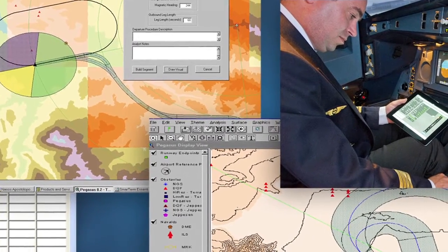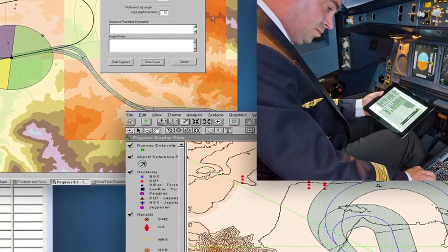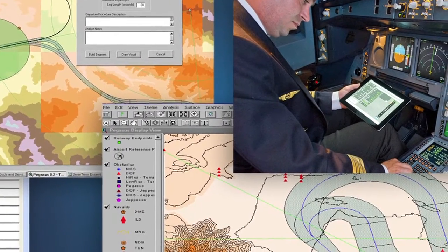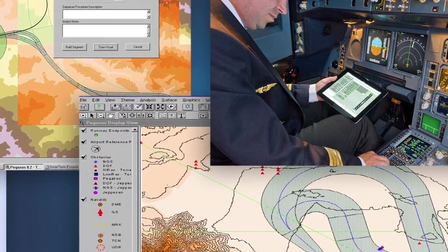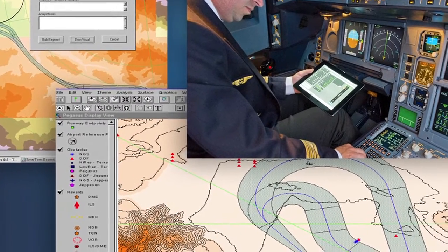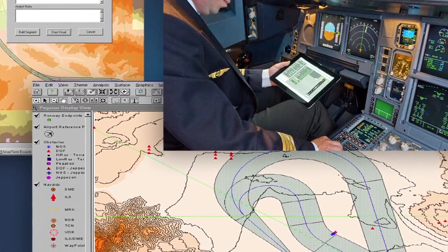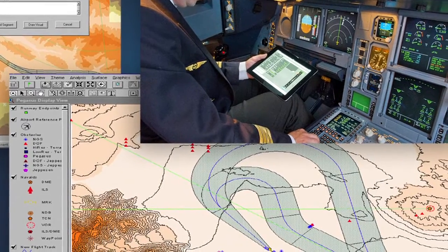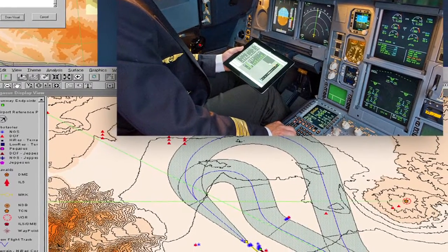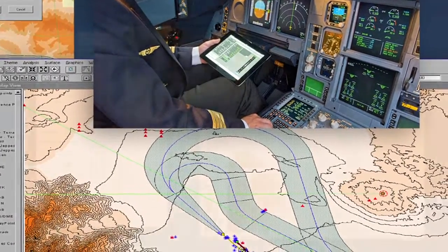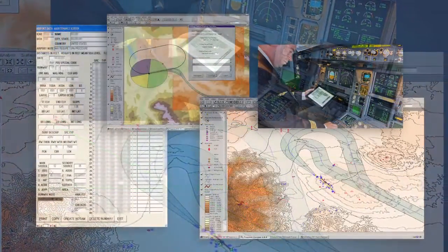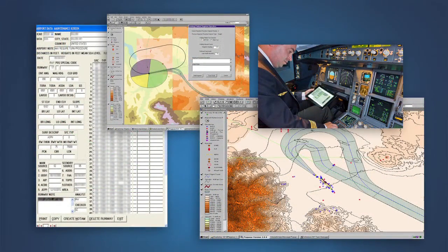Performance engineers will most often use the airplane flight manual data to create a more practical means for pilots to evaluate obstacle clearance to support flight operations. Examples might include a software performance calculation tool, such as might be installed in an electronic flight bag, or a runway-specific airport analysis, summarizing the limitations for departure from a given runway. However, even these tools are dependent on a properly maintained obstacle dataset.